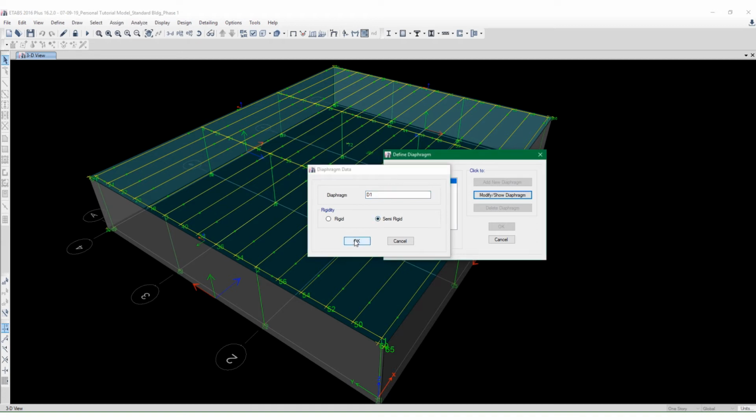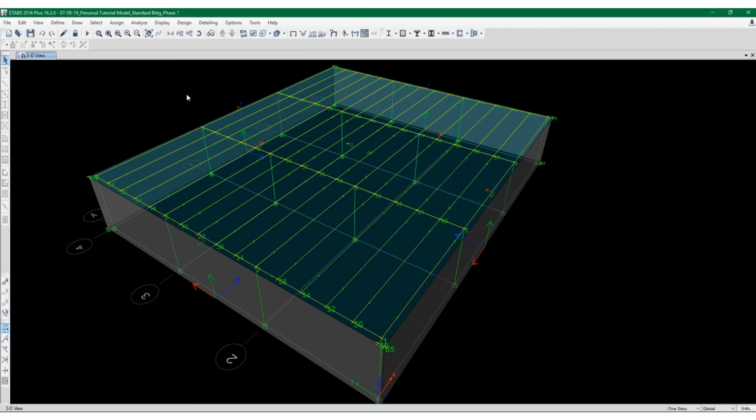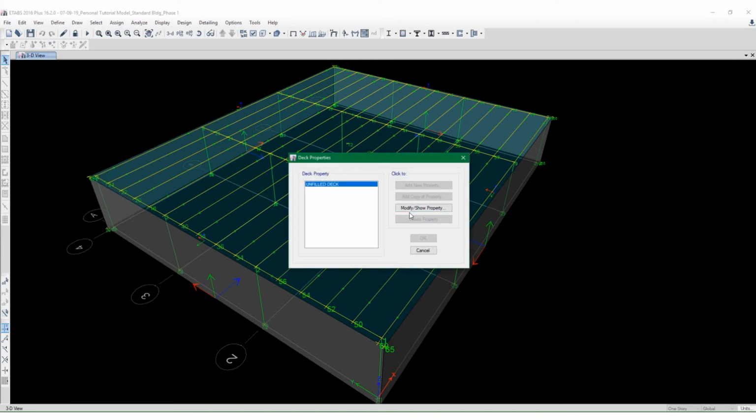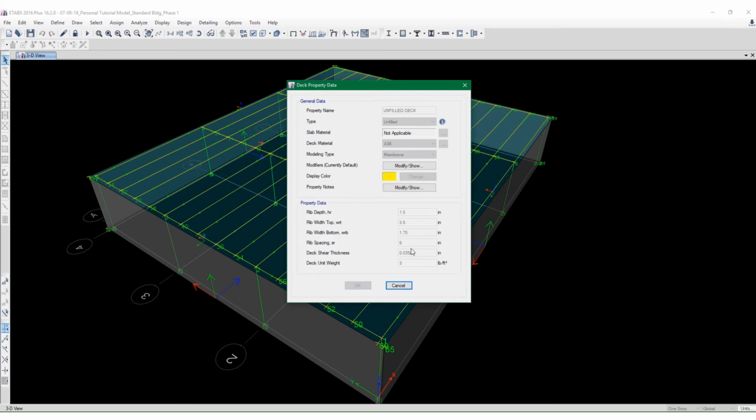And when you combine that with the meshing that takes place with our unfilled metal deck, you can see that the properties of this unfilled metal deck result in flexible mechanical properties. And so we were getting very large deflections on the ends. And I suppose it's fairly rational as far as having that type of deflection.